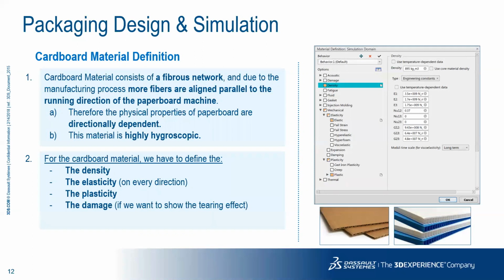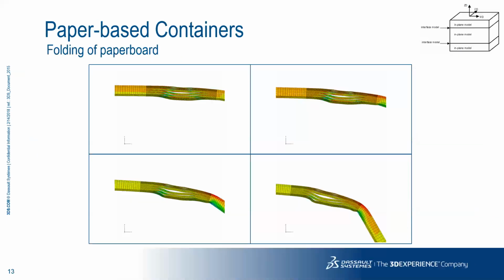We need the possibility to define plasticity, so once it deforms, if it does not recover. We also need the framework to define damage, so if it damages, would it be able to recover? These are the material models which are available inside of Abaqus out of the box. Often we require much more advanced techniques, and for that you can use the user subroutine approach, which would allow you to go after it.